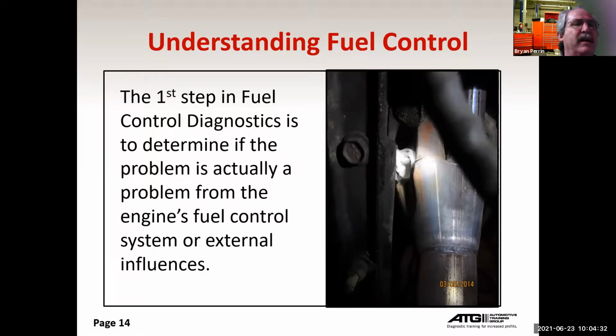Some manifolds, like some of the Hondas, are dual manifolds where they have an inside and outside layer with an air gap in between. You really can't weld those because of the design of the manifold. If you're getting exhaust out, it's had to go through 2 layers, so it's compromised. You need to replace it. There is some stuff like that out there, but as far as the length of the crack, that doesn't deter me. I've built a lot of exhaust systems.